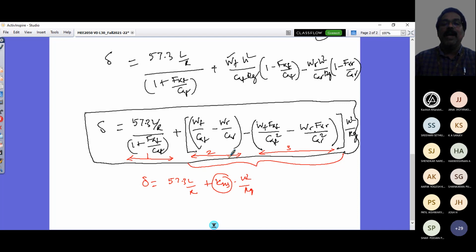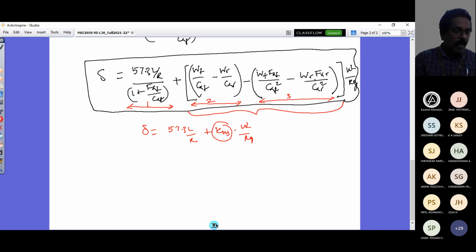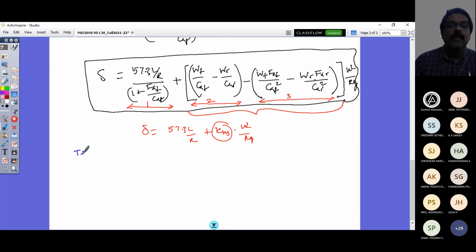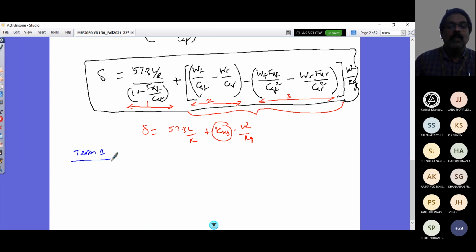So now let us look at and interpret more of this equation from these terms. So term 1 here, what is the influence of this term 1? You have to understand this. This is the Ackermann steering angle alteration. The Ackermann steering angle is altered by the tractive force on the front axle. The rear tractive force does not show up here. That doesn't come, so FXR doesn't come.